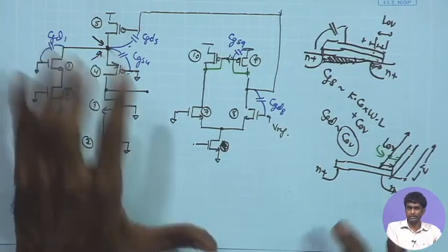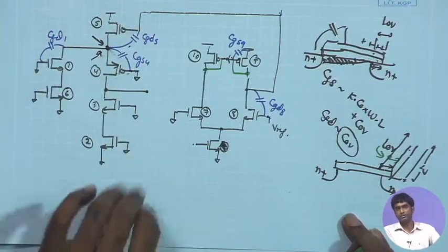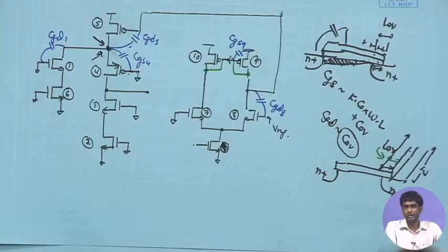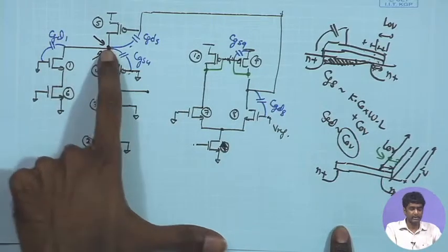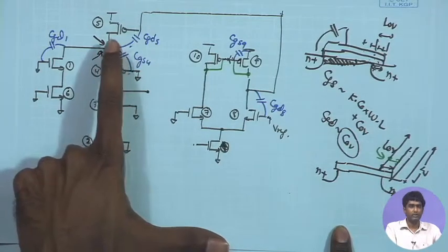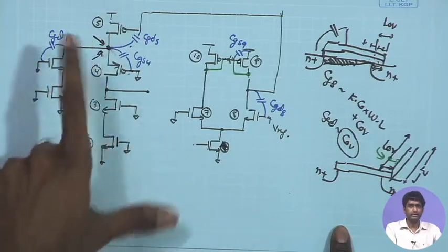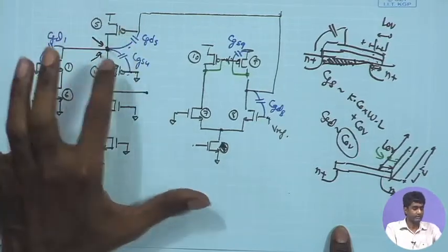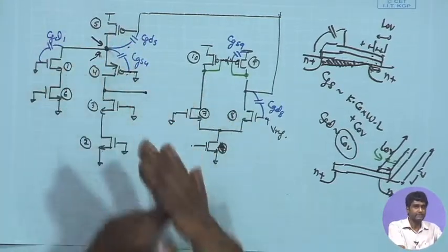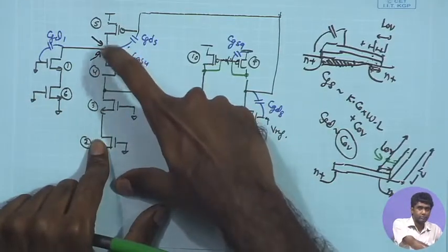So, by taking appropriate design decisions, I can try to minimize this combination of these three capacitances, so that they do not interfere with my dominant pole compensation. So, the summary out of this is we just identified what are the capacitances coming in at this second pole, then we looked at the dependency on the dimensions, and then we are also trying to see how, following other design constraints, when we are trying to size different transistors, those sizing issues are going to affect the total capacitance over here.